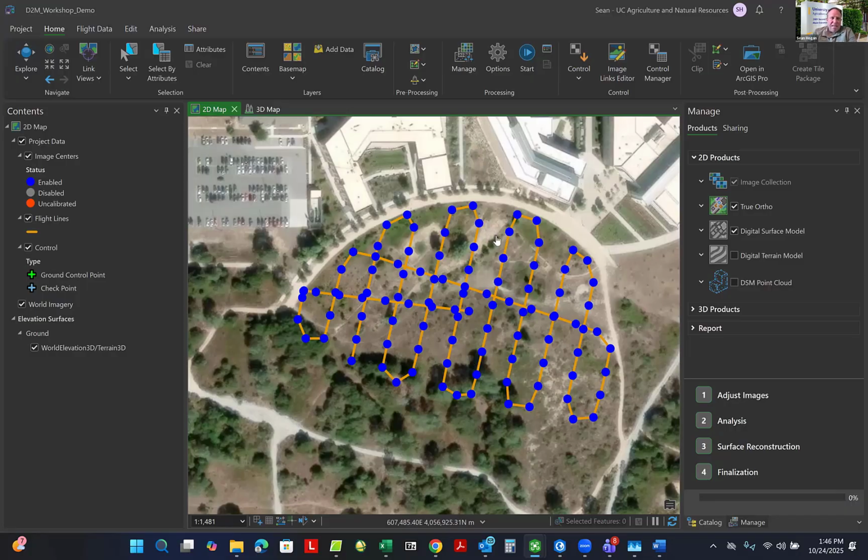And once that's in there, there's a bunch of other options across the top that you will see, and I'll come back to those in a little bit, a more robust way of processing for multispectral data. But most of you would just go in and click. First you would check across the right-hand side under Manage. You'd probably include Digital Terrain Model. That used to not be available, as I understand it, in the standard version, but now it is.